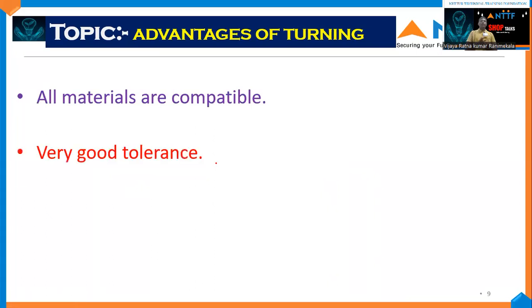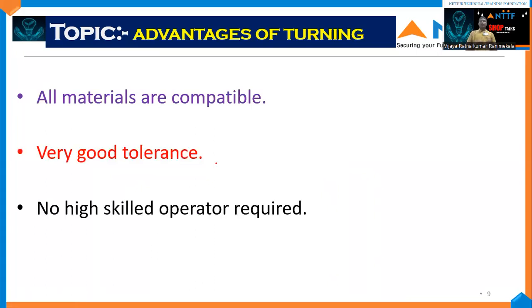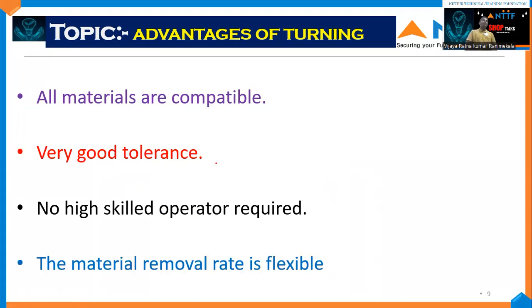Let us see advantages of turning. All materials are compatible. Very good tolerance, better than compared to milling. No high skill operator required, because even a laborer can do it. The material removal rate is flexible.